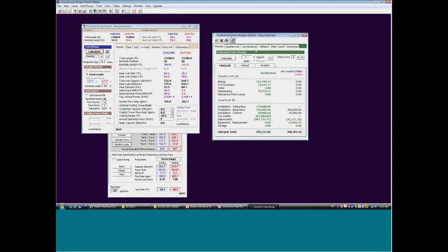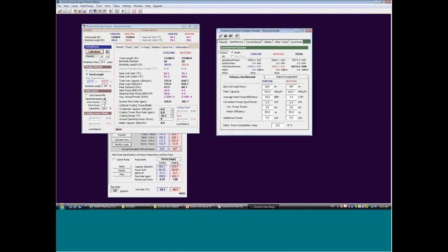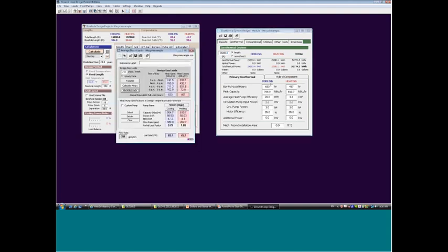So we can start over here with our geothermal tab. The first thing it brings in is the length of drilling. We're drilling 15,200 feet. It brings that in so we can calculate the cost of that. Brings in my cooling loads, which we can see here, 633 hours, 457 hours for heating. See, these are right here. Brings in my peaks, 755 and 810. That information alone gives me my total cooling load and my total heating load.